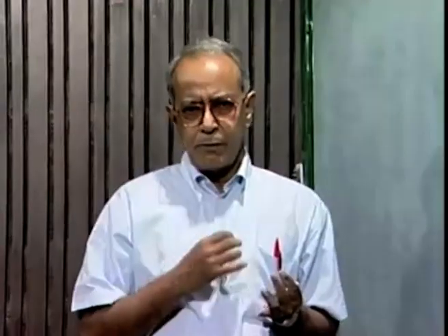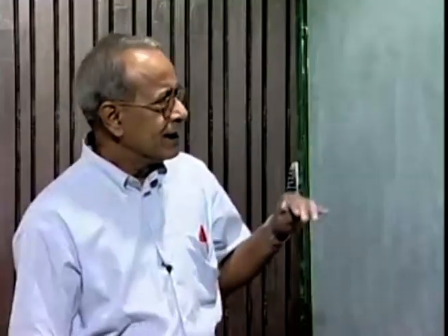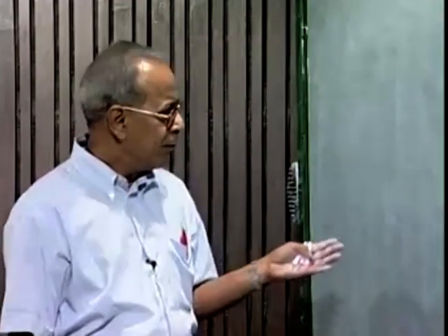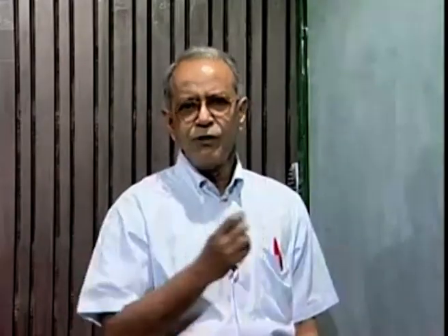Now that we have discussed all types of basic follower motions like uniform motion, simple harmonic motion, parabolic motion, modified uniform motion, modified parabolic motion, or cycloidal motion, we have seen there is one kind of difficulty, that some derivatives of the follower displacement like velocity, acceleration, jerk, etc., may be very high at the beginning or end of the rise, or at some intermediate point during the follower movement.